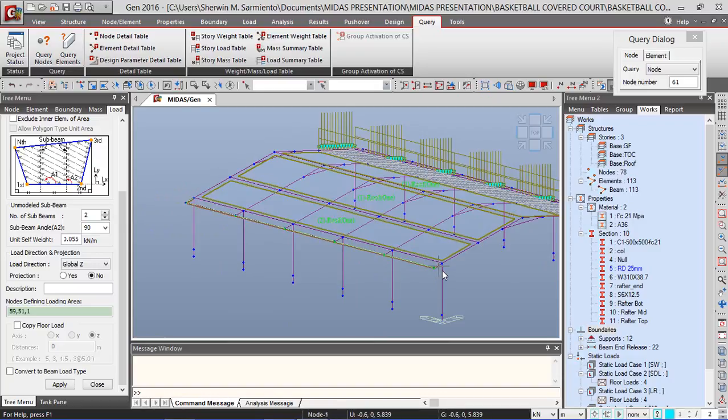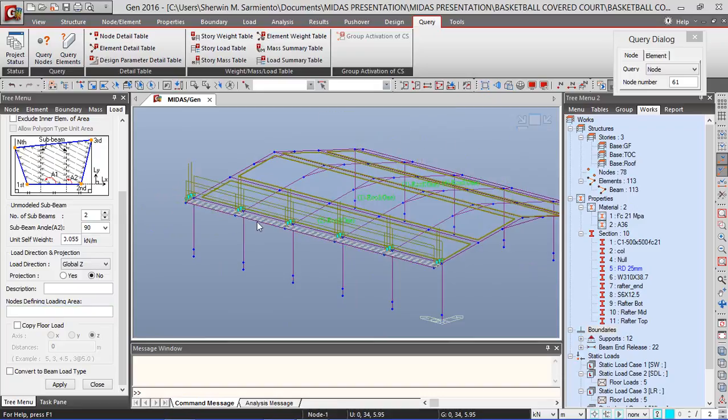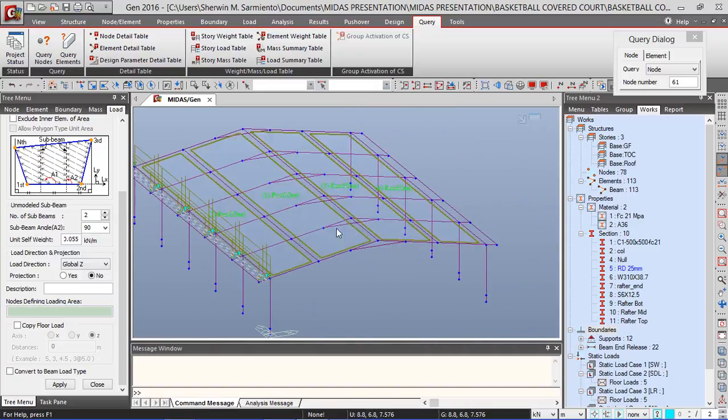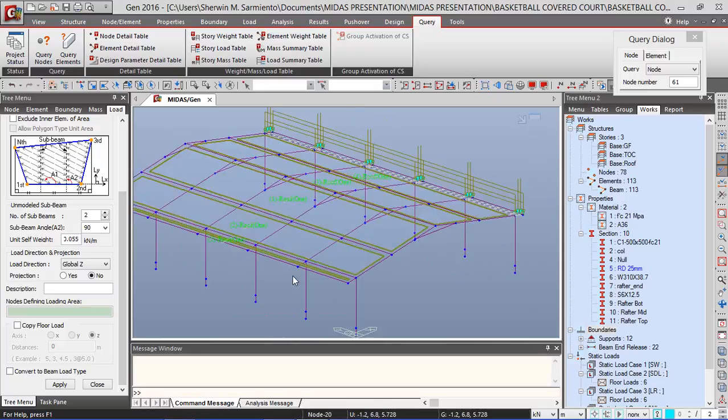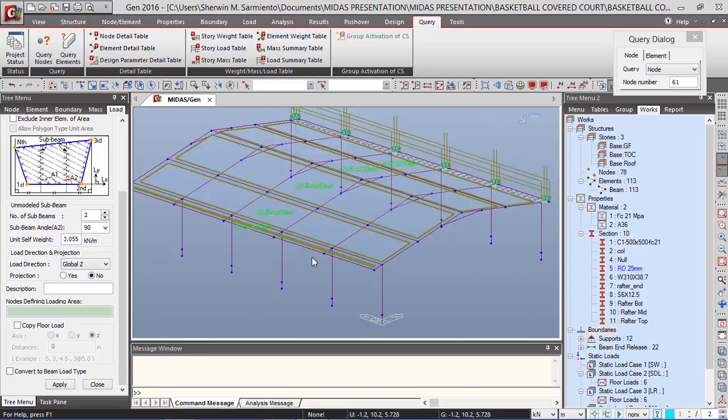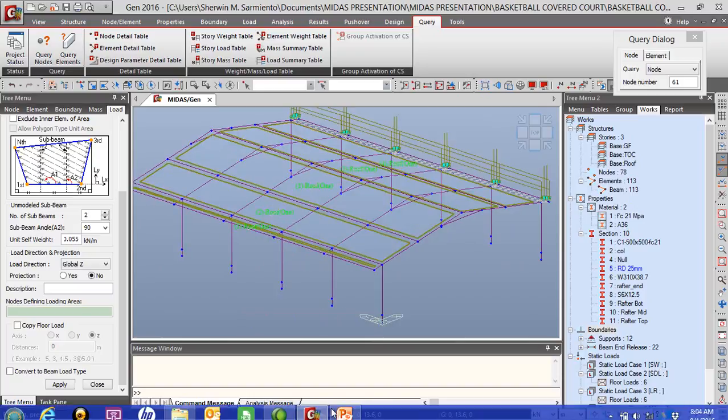If you don't add this null section for cantilever sections, it will not apply it. It will say that it's cantilever and it will not apply it. So this method of applying a non or low stiffness member helps really well with this method. So there, I'm finished applying the roof dead loads and live loads, and now I can go to the next.